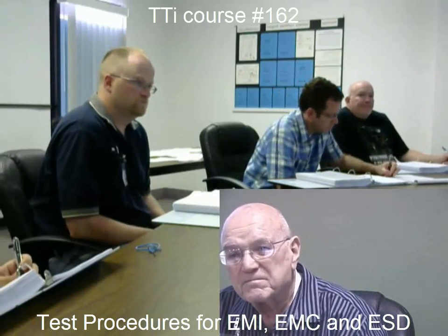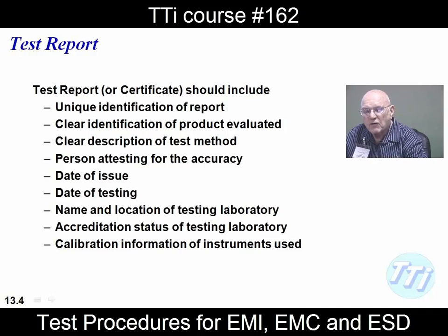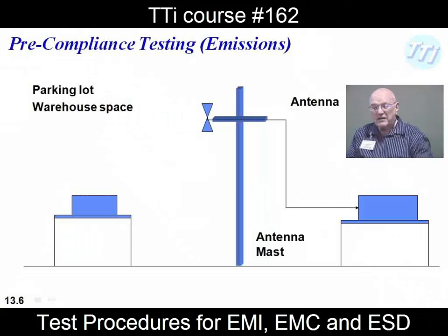And in there they actually have a complete list of accredited laboratories for all kinds of tasks, including EMC. And of course, calibration of the instruments used. Like you said, there's a question you got answered specifically. What happens if the instrument's out of calibration? In the Atomic Energy Commission, we found out that you've got to retest everything that you tested before. Don't have to worry about that with pre-compliance.